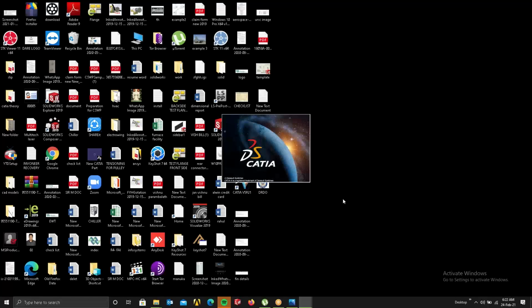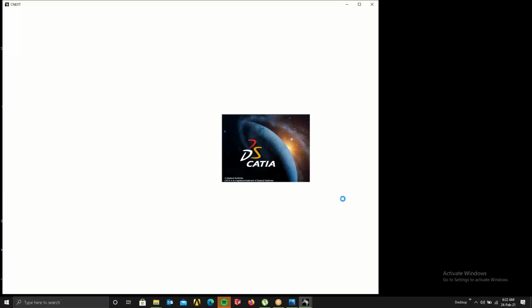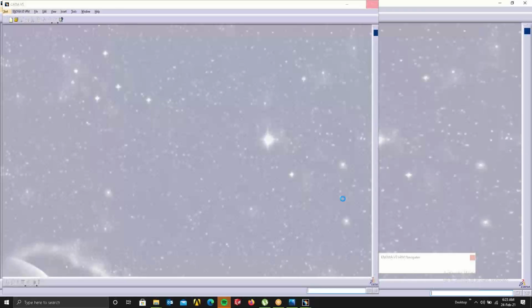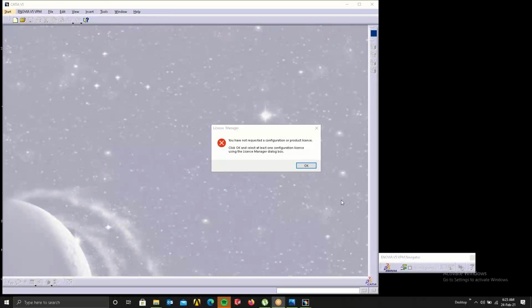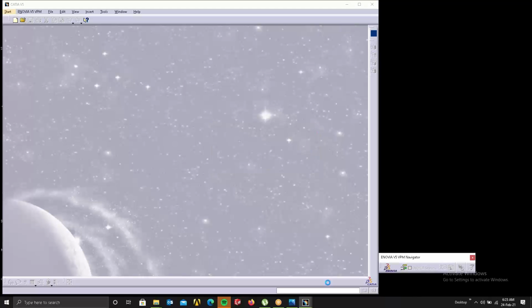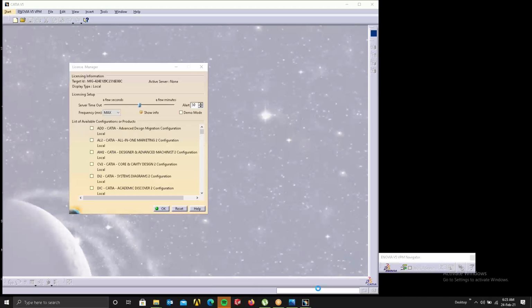There are two types of constraints, dimensional and geometric. Dimensional is just applying dimensions, and geometric is based on parallelism, angles, perpendicularity, concentricity, something like that, right? Yeah. Those terminologies are important for one more thing.